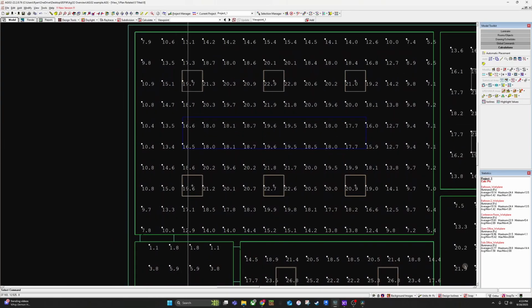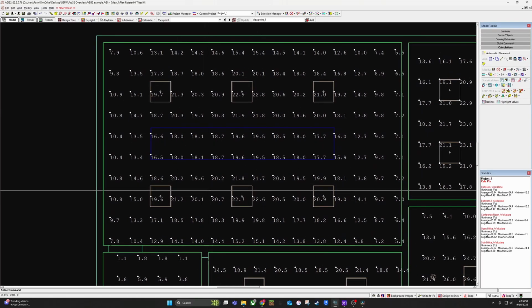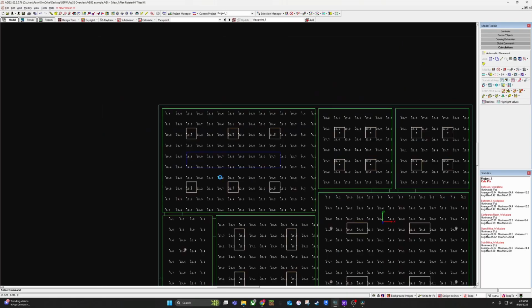So this table is 2.5 feet tall, and these calc points are also 2.5 feet tall. We don't need to delete these calc points here, but let's say that the work plane here is at 0 feet. It's on the floor. We have calc points going through the table. Then we would have to go through and delete these, but in this case, we do not have to.